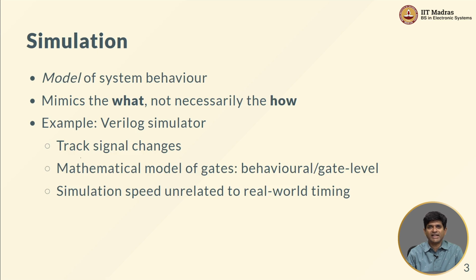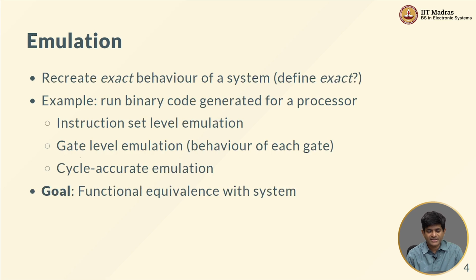And in general, the speed at which we simulate is unrelated to real world timing. We usually have some notion of a clock, but even the clock after all is just a signal within Verilog. We have some notion of so many nanoseconds passing. There is an internal notion of time within the Verilog simulator, but as such it need not have anything to do with how time passes in the outside world. To summarize, simulation is a slightly abstract concept. We are concerned with the model of the system behavior. So what's this other term that we come across on a regular basis?